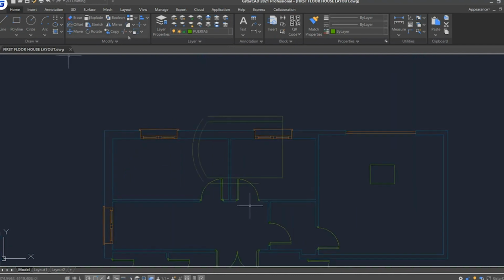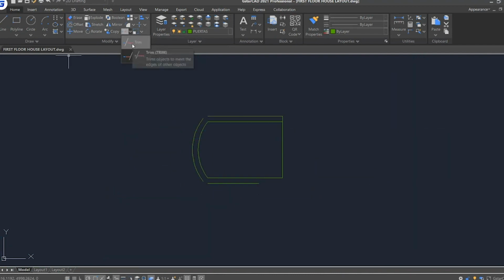The opposite of the trim command is extend. You can shift to extend when you have already started the trim command. Select the boundary, press enter, then press shift and select objects you want to extend. The dashed line will preview the result. Press enter to end the command.